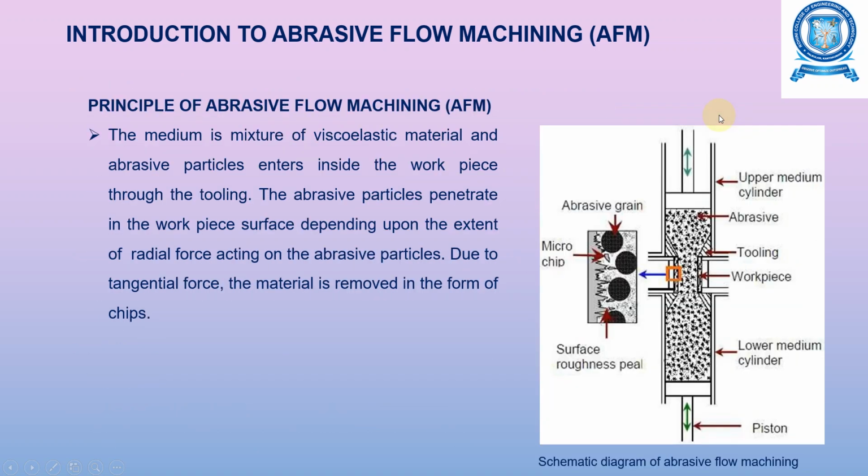So, principle of abrasive flow machining. The medium is a mixture of a viscoelastic material and abrasive particles. It enters inside the workpiece. So here is a workpiece, and then through the tooling, this abrasive and visco material mixture enters.